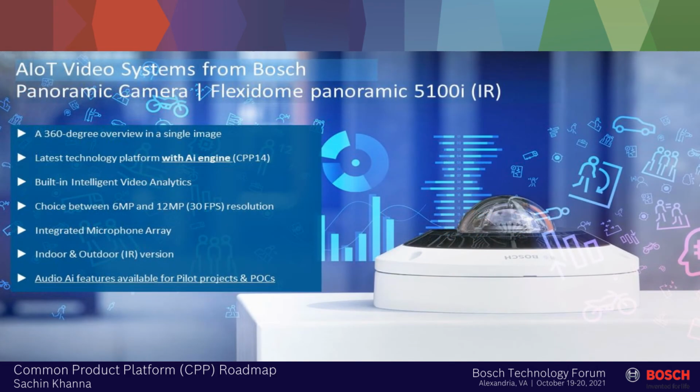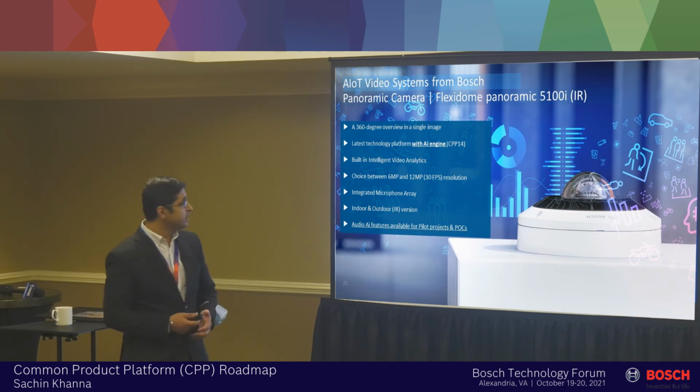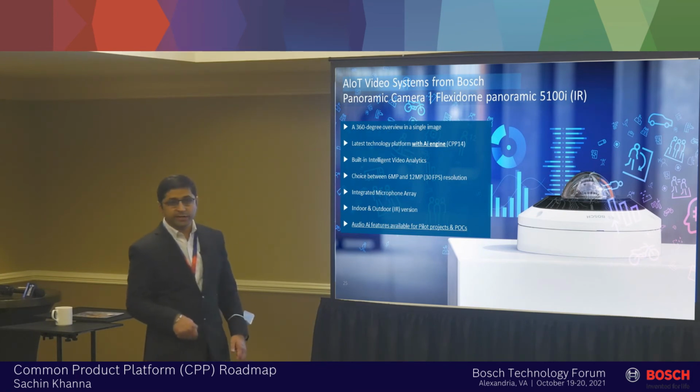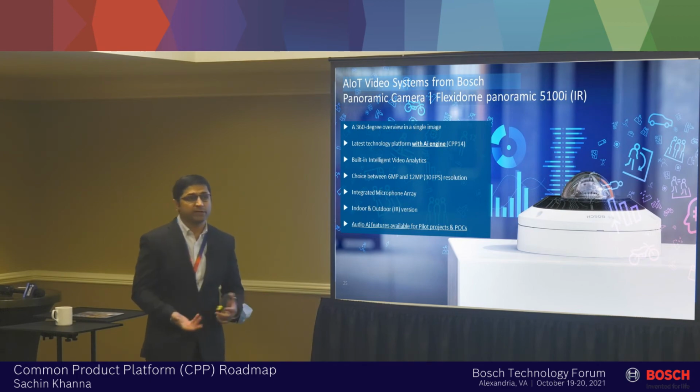Then I talk about CPP 14. We had this session in the morning where we talked about the cameras with the gunshot detection, audio analytics capabilities. This is part of our CPP 14 product. So this Panoramic family is one of our first products which bring the CPP 14 to the market. Over here, we are running our latest AI engine. So this will run video analytics on it, plus also for certain applications, you can also have audio analytics running on this camera. We support on this a 6 and a 12 megapixel, again, a dewarped image at 30 FPS. The camera comes with an indoor and outdoor version with and without IR.